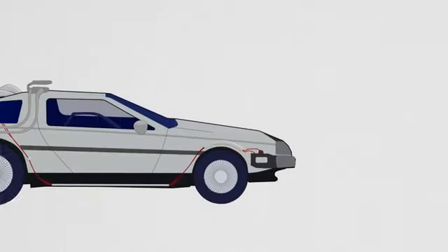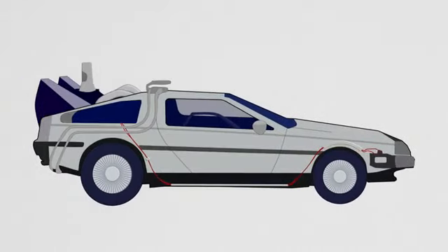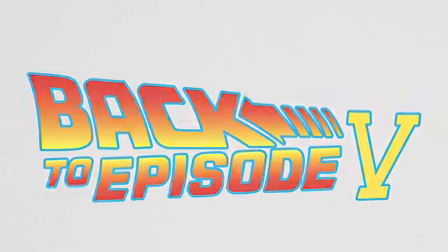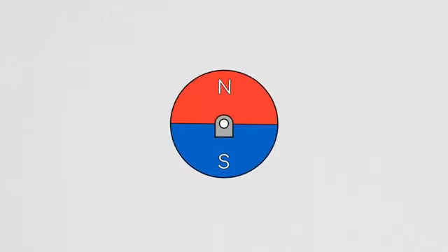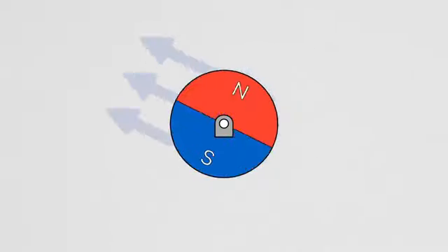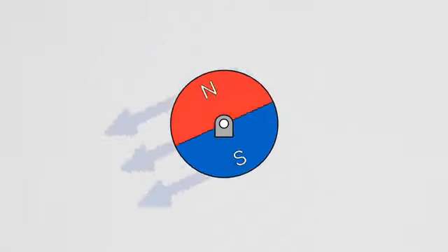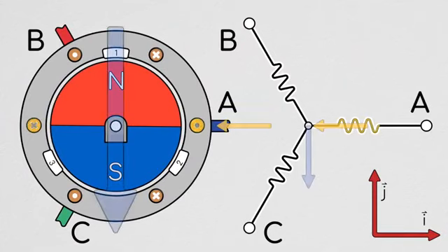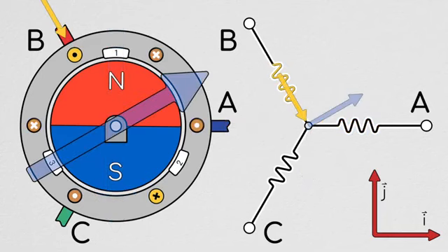We're going to start today by briefly going back and changing some of our notation. In episode 5, when we were talking about the magnetic field alignment method of torque, we learned that in order to maximize our torque produced in a brushless motor, we want our induced magnetic field to be orthogonal to and leading our rotor's magnetic field. In the notation I used that episode, the magnetic field vector generated by the stator of the brushless motor will be 90 degrees counterclockwise from the current vector, as shown in the motor winding diagram.